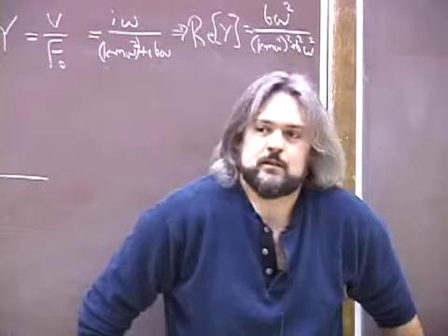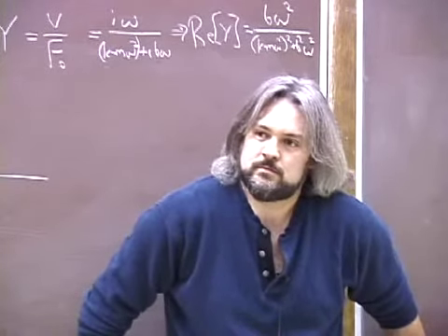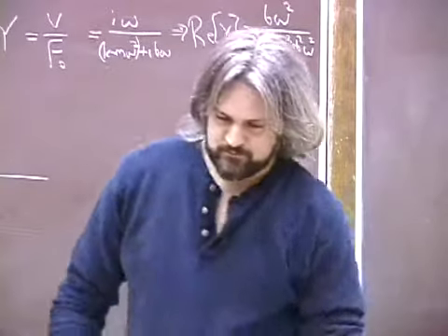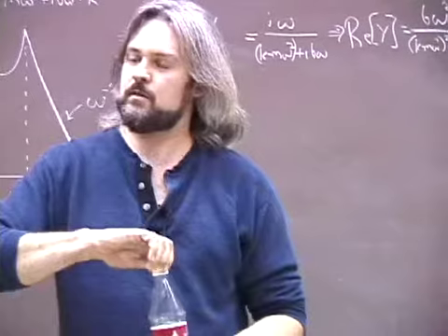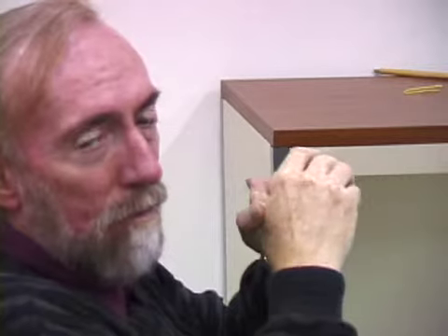Or if you remember, S sub x of omega, when I motivated it, came from the theorem that relates the integral of the square of the Fourier transform. Some people call it Parseval. Yes, it's Parseval's theorem. And so this is basically the frequency side of Parseval's theorem, integrated over frequency to get the mean square value of the fluctuating quantity x.